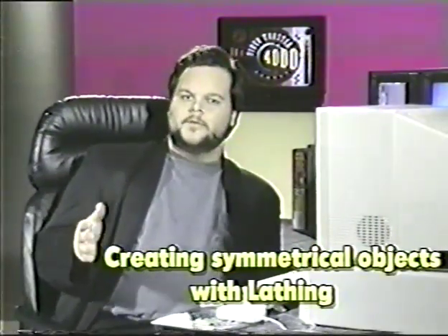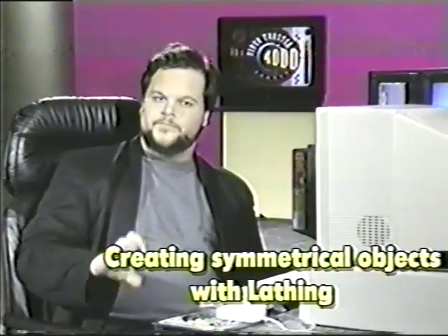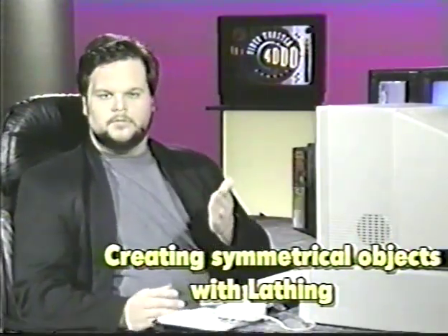So, like I say, a number of objects you can make with this, and it's important to understand how these offset and angle tools work. Now, this is one use for lathing, and this is one way to do it, and it's very handy. But there's another use, and it's actually a little more common for lathing, and that's that you use lathing to create symmetrical objects. A good example of that would be an urn or a pawn from a chessboard, something like that. And the way we use lathe here is very similar. We're sweeping it around. What we're actually doing is creating a half profile of an object.